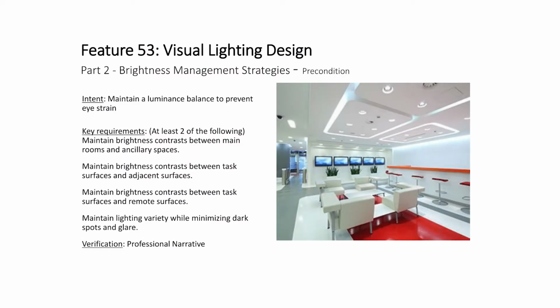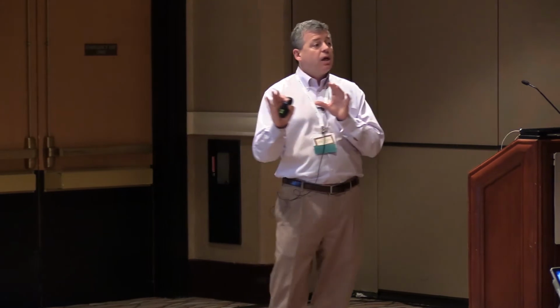You then get into this ability to balance light and minimize eye strain. It's really a tie into glare control. A lot of what that is tied to is not just your illumination from here, but your vertical surfaces and their illumination to allow you to have visual comfort. A lot of times that balance between the walls and their illumination and a computer screen is a very important piece of eye strain control.